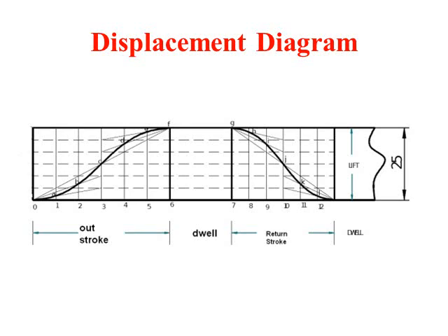Take the center, so it is 3 here, and this vertical line at 3 has to be again divided into 6 equal parts. So after dividing into 6 equal parts for both the outstroke and the return stroke, if you take the return stroke, here 10 will be the center point, and that has to be divided again into 6 equal parts.